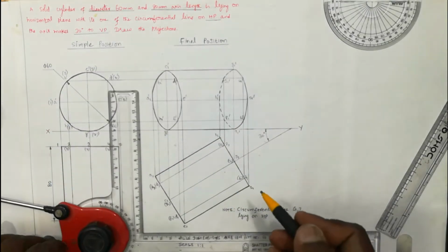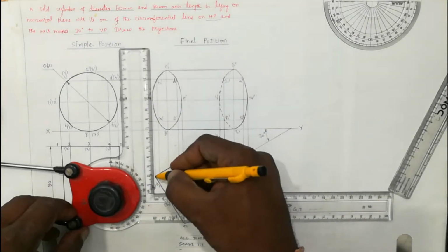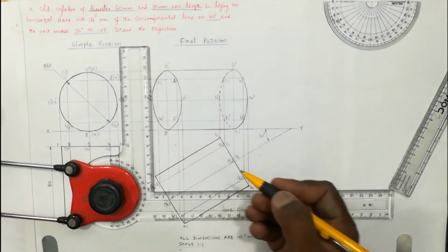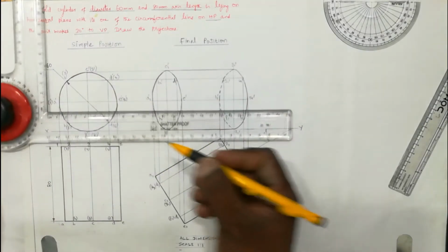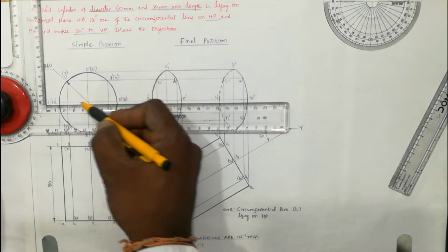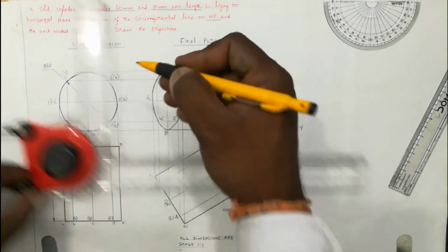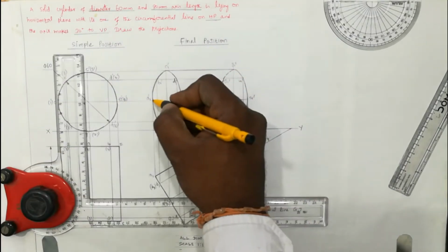From point A suffix 1, draw a vertical projector using the vertical scale of your drafter with a 2H pencil, and draw one horizontal projector from A dash. These will intersect at a point that is marked as A suffix 1 dash.